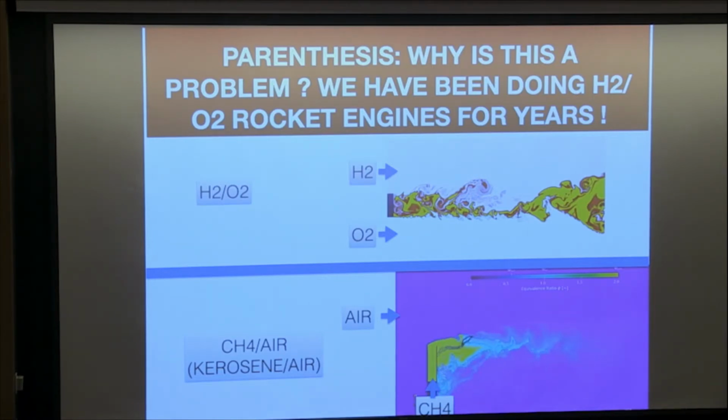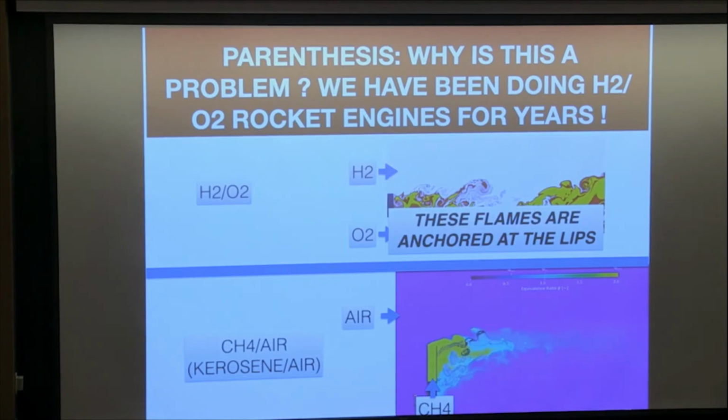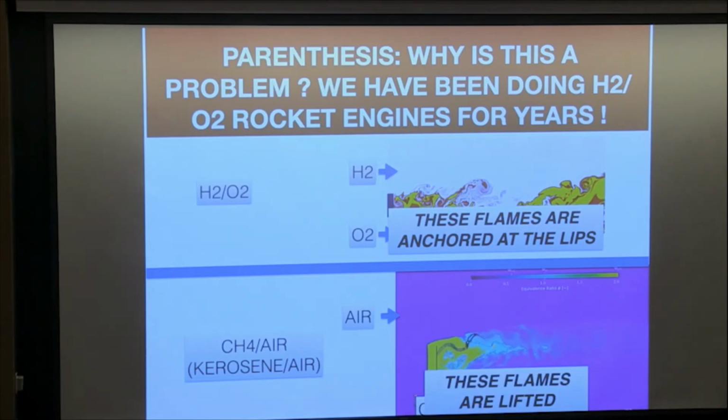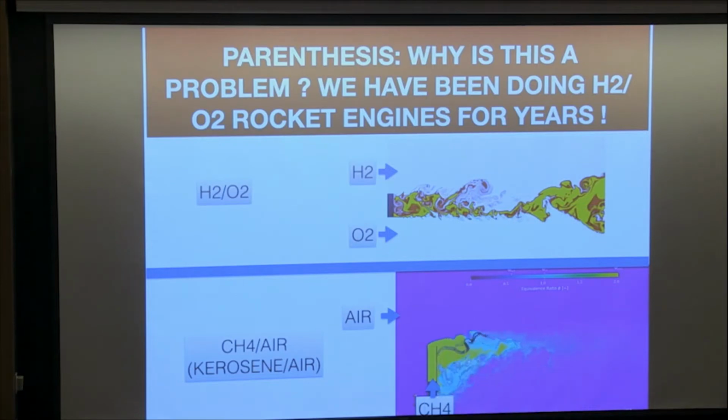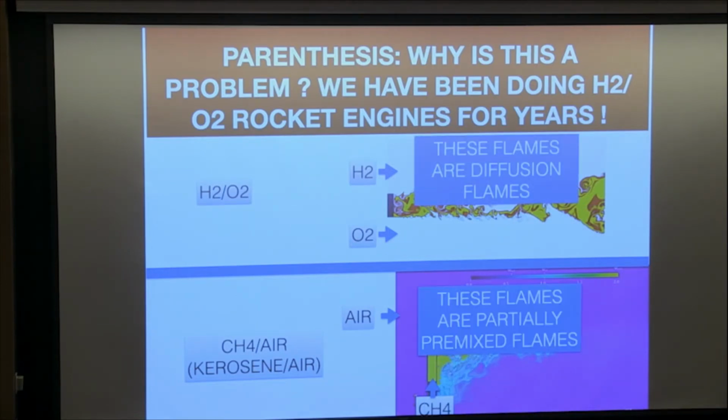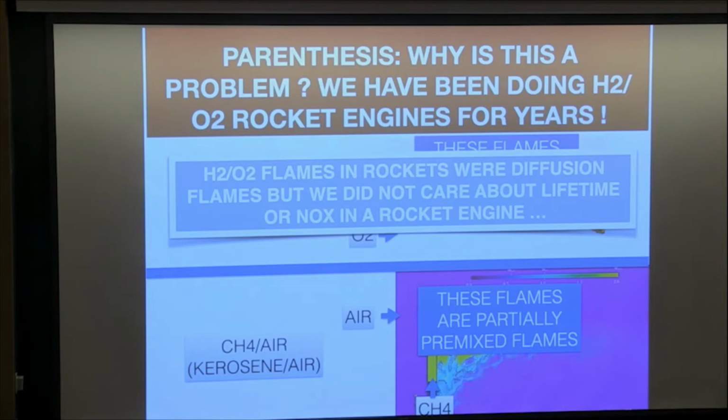And it is true that for H2/O2, all the flames were diffusion flames anchored at the lips of the injection, while the classical flames are lifted. In other words, those flames here on top are diffusion flames, and those at the bottom are clearly premixed. But the point is that in a rocket engine, you don't care about NOx, okay? You don't even care about the lifetime, okay? Because it's not a problem. But now we have to, if you go in an aircraft, it's a different problem. We cannot live with diffusion flames.